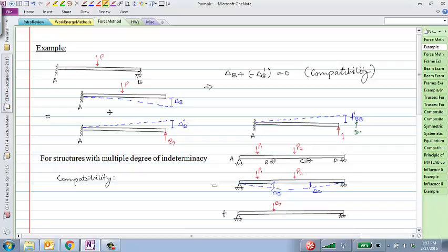The first B denotes that we are measuring the flexibility of displacement at B. And the second B says that there is a unit load at B as well. So this flexibility is essentially, if I apply a unit load at the tip, what is the displacement at that point? Other points have different displacements.